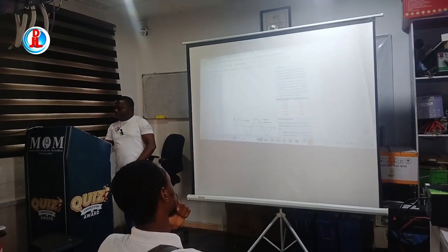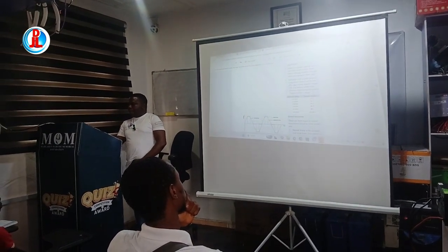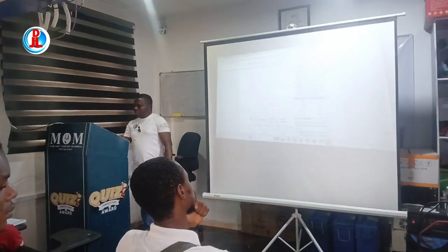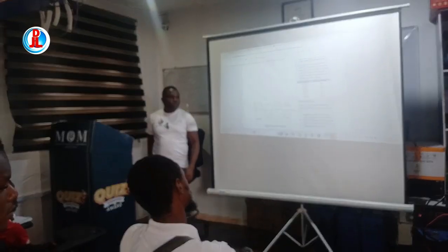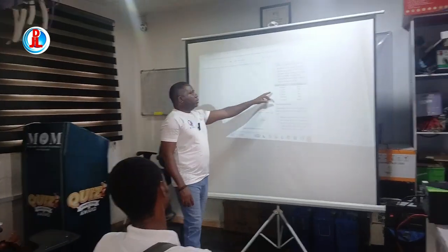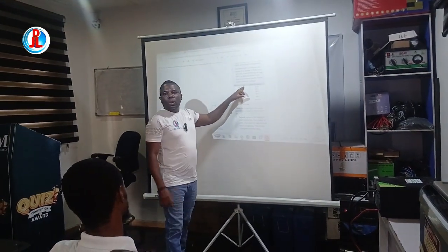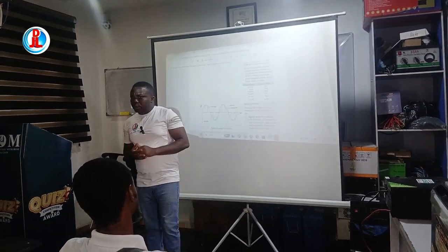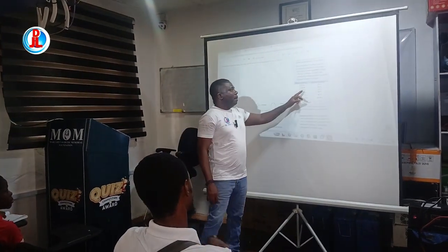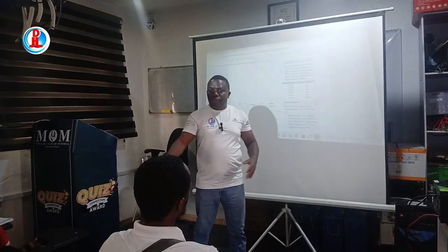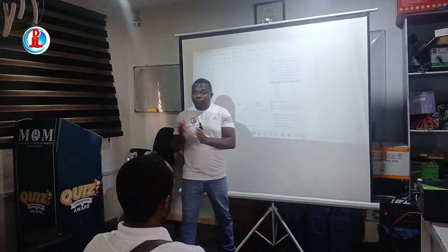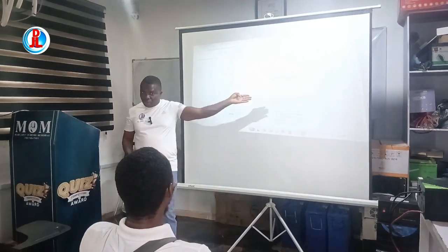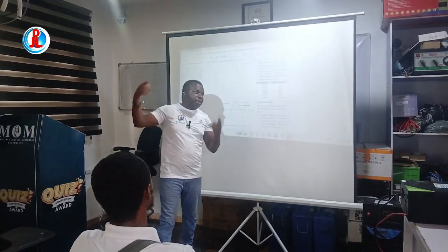Inverters with lower power output below 1 kVA usually use a low battery voltage. Now look at this. From 0.8 kVA to 1 kVA, we usually use 12 volts. From 1.5 kVA and above, we usually use what? 24 volts. But at present, I think there is a 2 kVA that is 12 volts. It's a modification to accommodate panels.